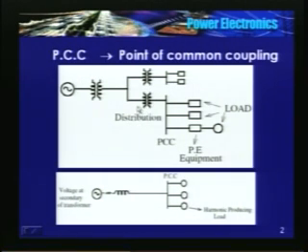It is received at the receiving station. Voltage is reduced here using a step down transformer, and it could be further reduced before distributing to other loads. So you may have more than one transformer. Consider the high power loads being fed from a medium voltage. All these loads are connected somewhere at the common bus, or this point is known as point of common coupling.